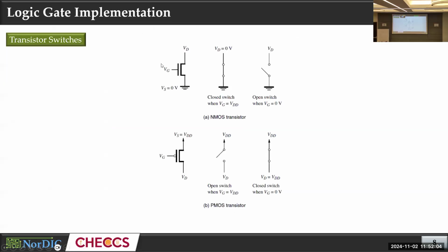Here, as you can see, VG means the gate terminal voltage, and it is VDD. As I have said, VDD means high voltage, means 1. So VG is equal to 1. Whenever you see VG equal to VDD, you have to interpret VDD as 1, simple as that. And 0 as 0. There is no problem with 0. 0 volt is represented as logic 0. But when you see some voltage equal to VDD, that means it is logical 1. We represent this as 1.